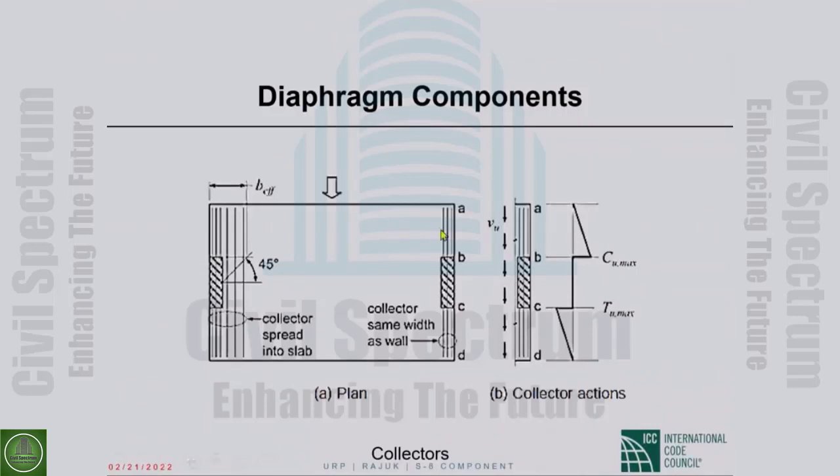Now, if the entire diaphragm edge were supported on a shear wall, it would have been direct shear transfer. The diaphragm edge shear would be transferred to the shear wall, and that's it. However, in this case, we have 60 feet of diaphragm edge, 20 feet of shear wall. So the shears over the 60 feet have to be collected and delivered to the shear wall.